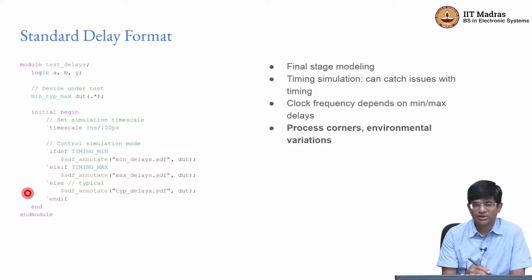That also relates to the idea of the so-called standard delay format, right, which is usually the final stage of modeling. After you have created a circuit, you have done everything as far as the implementation is concerned, you want to run through a simulation where you actually take into account the delays through gates and make sure that everything is working properly, right. This is so-called timing simulation. It can catch certain issues that might come up due to timing errors in your design, right.